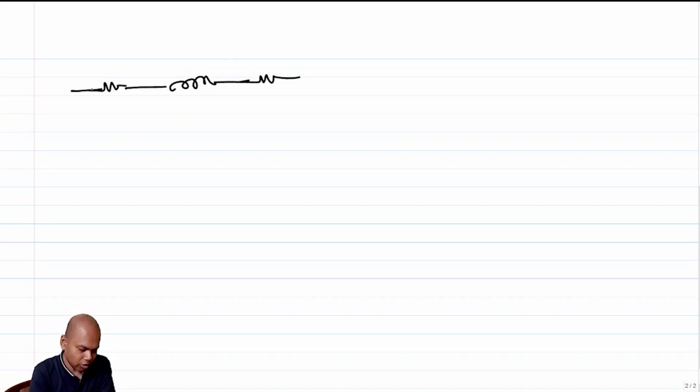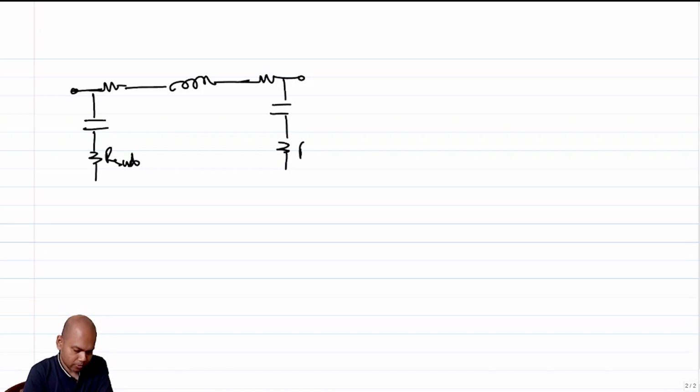So for example, the inductor model that I showed you in the previous lecture was something like this. So this is your main inductor. You have lossy R's here, and these lossy R's can be the physical series resistance, or due to skin effect, or due to proximity effect, and so on. They are lumped into this resistor. And then you can have some substrate coupling and the resistance of the substrate also contributing to some loss.